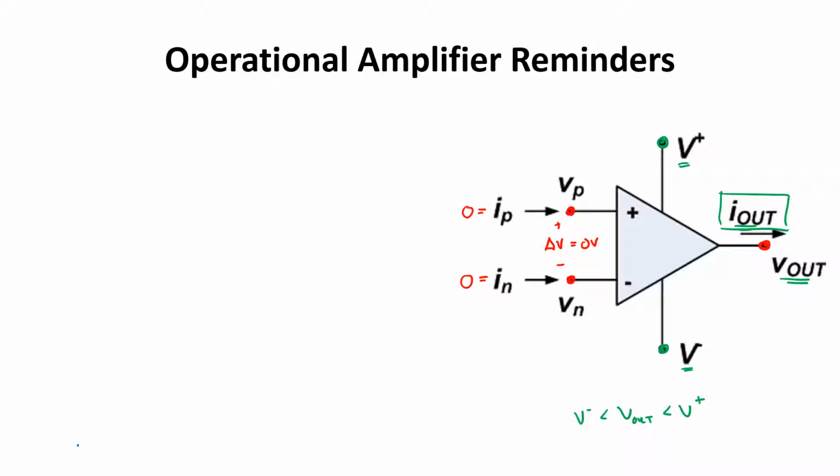Finally, there's one very important point relative to the voltages on this diagram. All of the voltages should be relative to the same reference voltage. In general, this will require that you physically interconnect them to ensure a common reference.